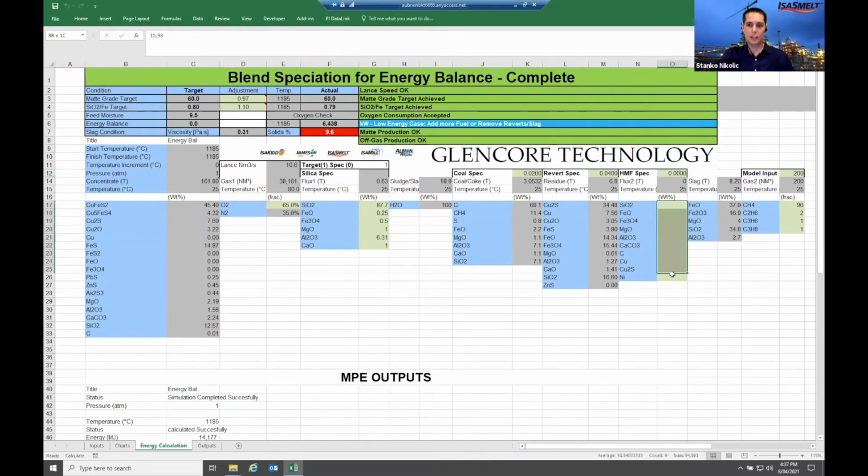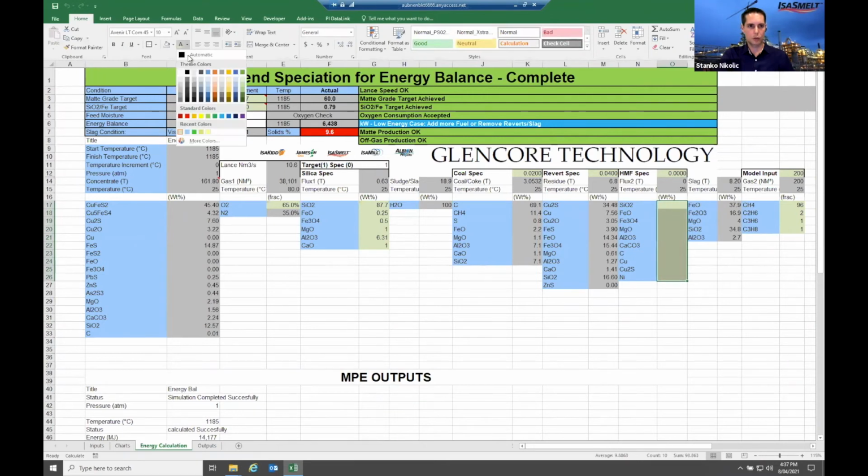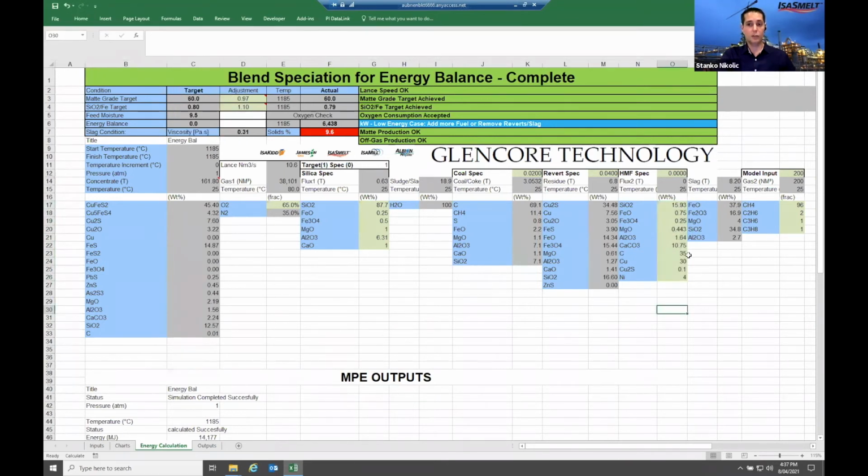Now, in our case, let me bring up this composition for everyone. This could be something that has a high level of organics and copper. This could be some type of scrap that we could put in. In the ISASMELT, the nice thing is that we're not bound by having to just add this material in with the feed. We can inject this material also down the lance, which is done on a number of our installations, and then look at treating it. So we've put in this high margin feed, which has some additional fuel value that it's putting into the system.